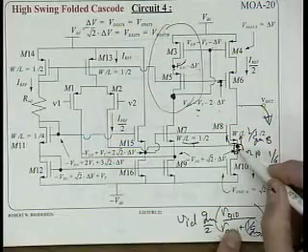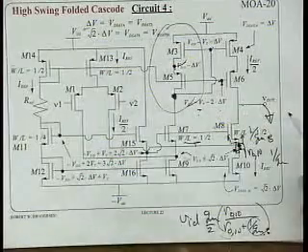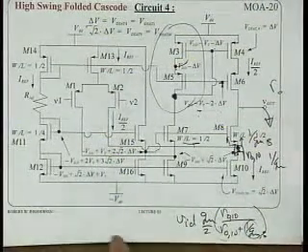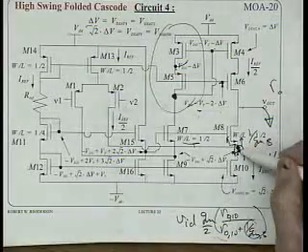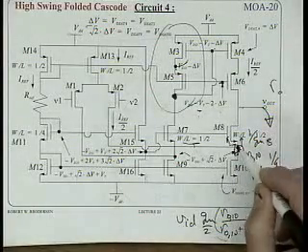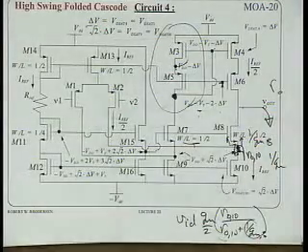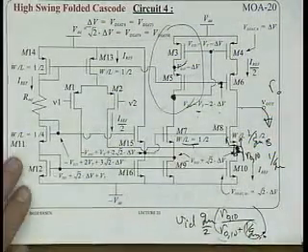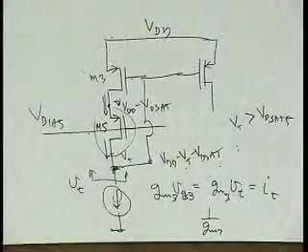This doesn't give us any stability problems. What we have to worry about for stability problems are multiple stages that have a high output resistance, like R0, like 2 cascaded common source stages. Because this is a really low resistance, the frequency response of this stage is really high frequency and it doesn't cause any problems with our stability. We'll talk about that a little bit later. A little foreshadowing. Any questions about that?